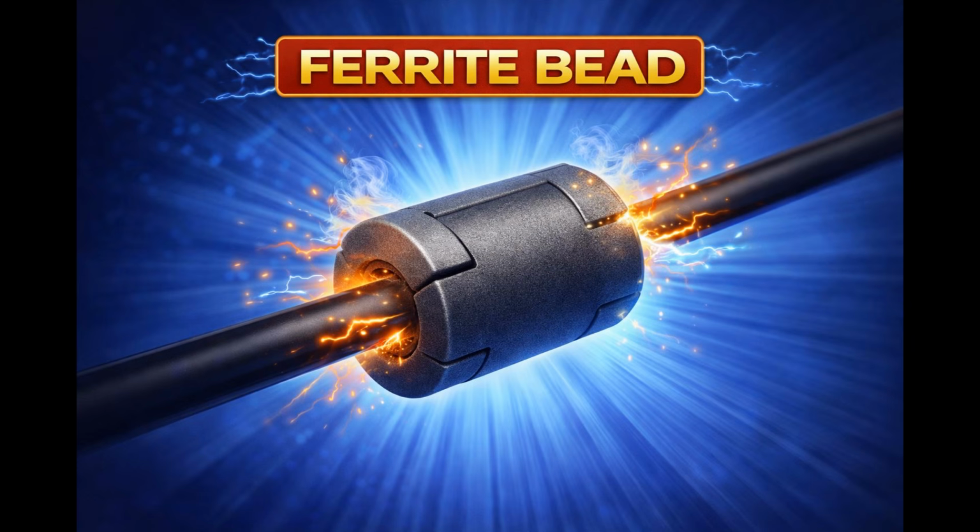In this way, the ferrite bead acts like an RF sponge, soaking up noise that would otherwise travel along the cable, interfere with equipment, or cause unwanted radiation. In radio systems, ferrite beads help reduce common mode currents, minimize interference, and improve overall station stability without changing the signal you actually want to transmit or receive.